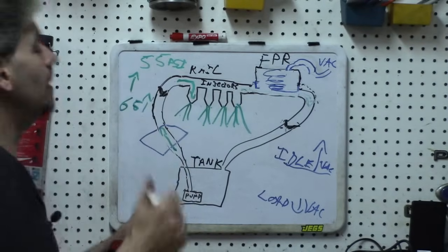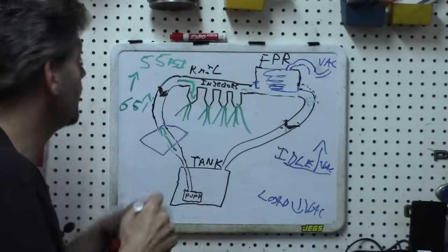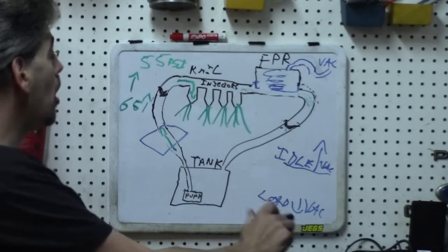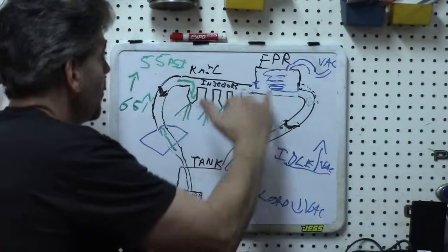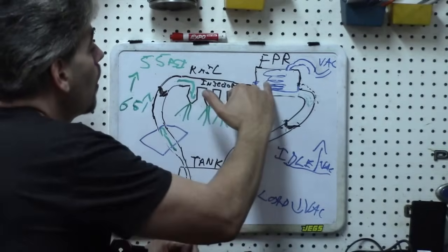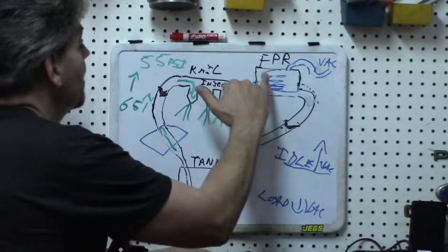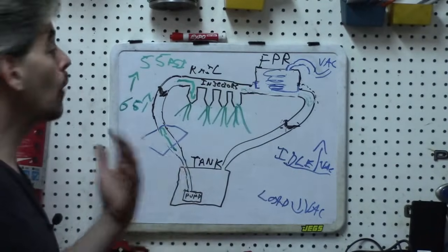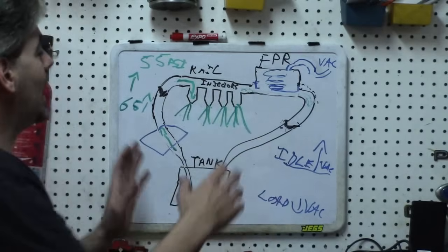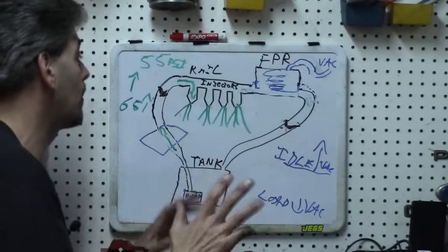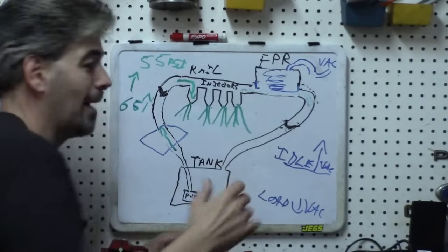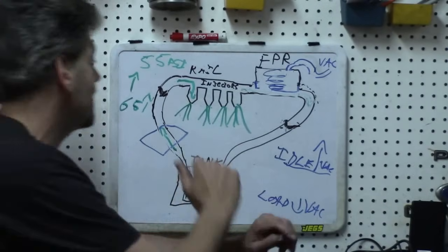to drop your static fuel pressure with the engine off, then you know that you either have leakage in the injectors, leakage with the line somewhere here, or in the case of an internal regulator, you may have an internal regulator leak. Make sure, of course, again, that if you do this, that you're blocking off only on a rubber component. Don't block off, obviously, a metal line or something like that.